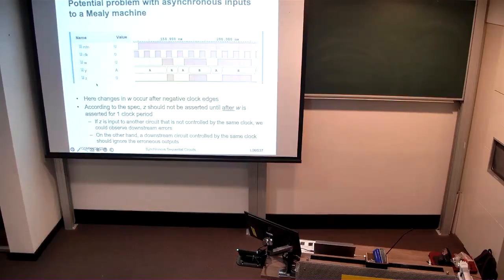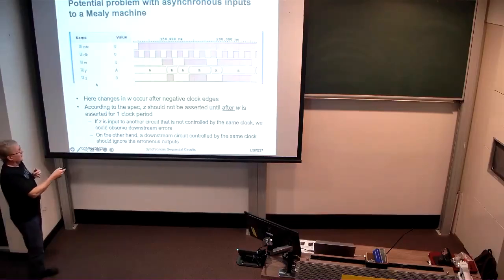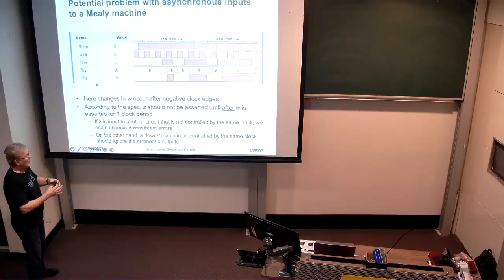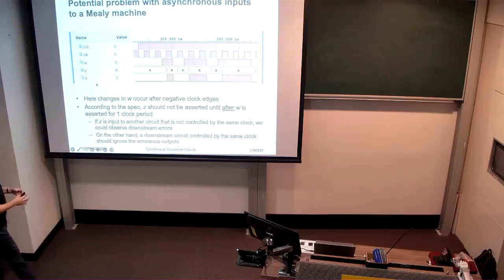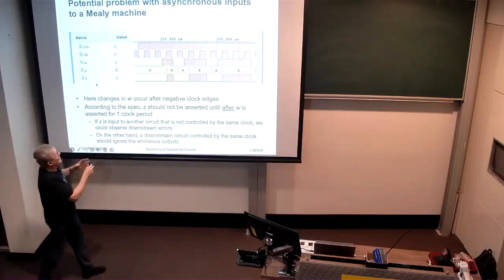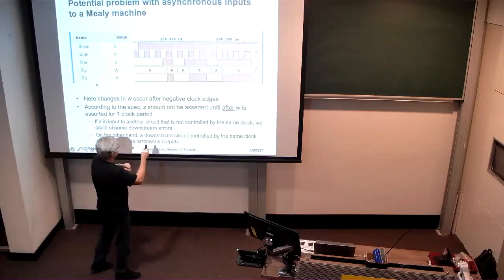It becomes a little bit more critical when that offset between when there's a change in the input and when the clock edges come along happens. Here I've shifted the input by half a clock period. Now the input rises on falling clock edges, and so you see a slight additional delay.